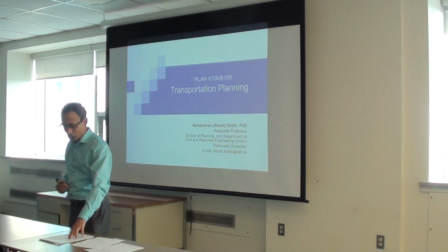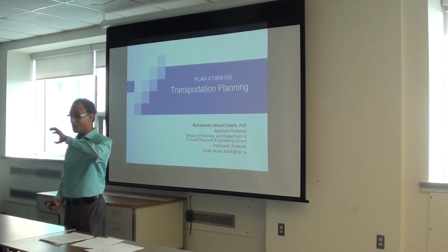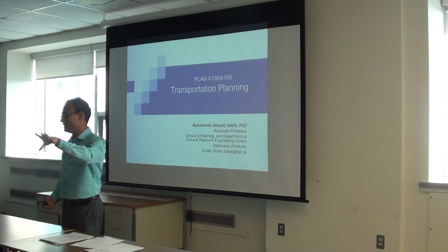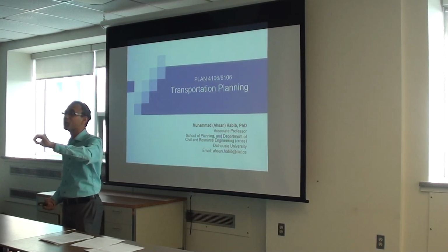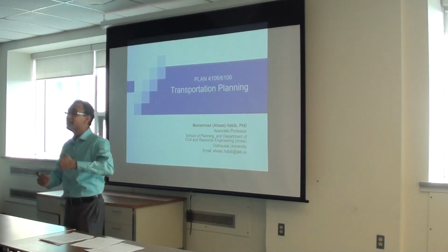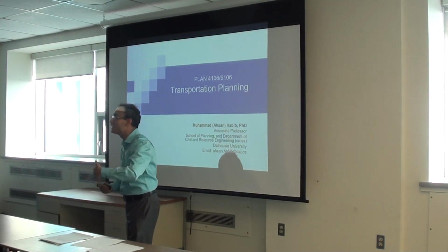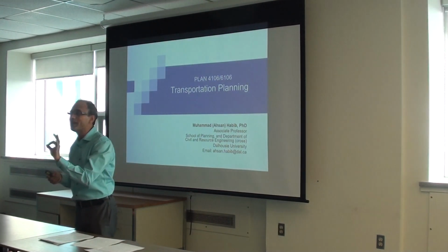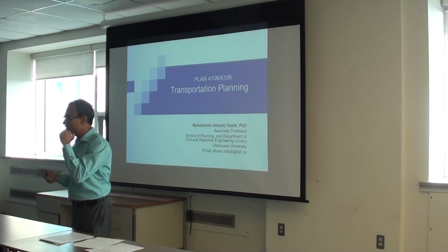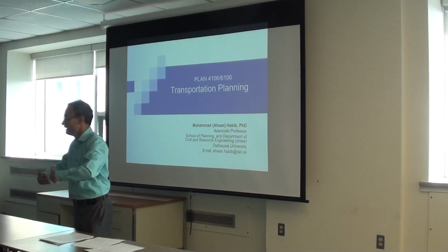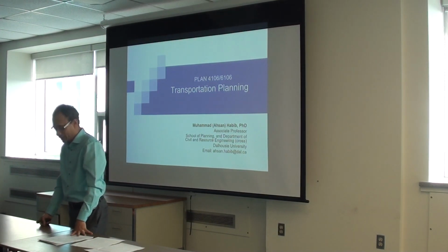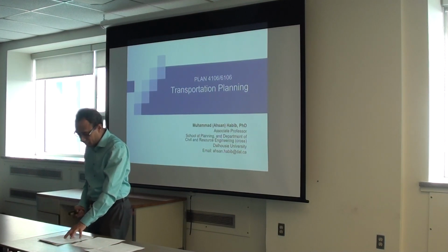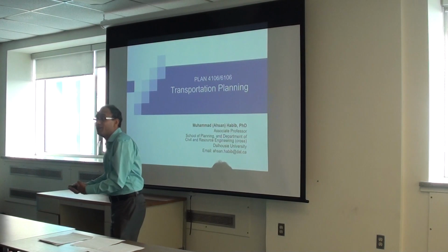The next stage is route selection. Once your corridor is finalized and you know some of the technology, say I will put some TPM, traffic priority measures, or queue jumping, or some design changes in there, then you finalize the route. You refine the route, the exact route, and you do not do evaluation on that. It's more that you see whether that's feasible for each. You propose in certain ways, right? And then select the final BRT route connecting a specific suburban area and downtown area, and you put rationale.